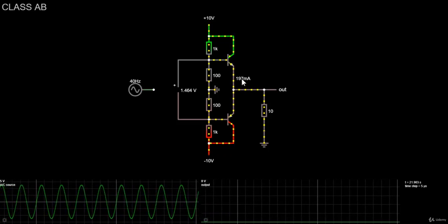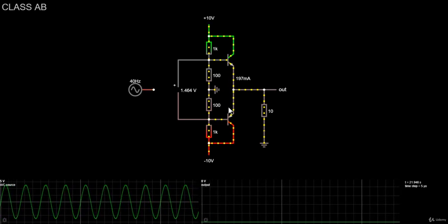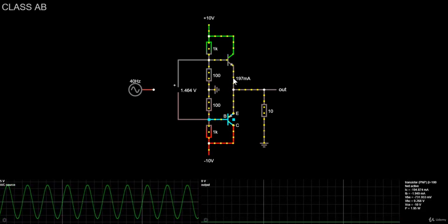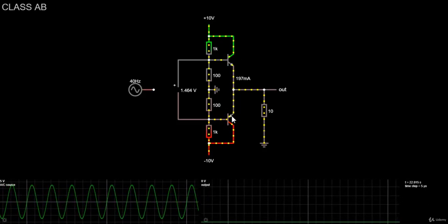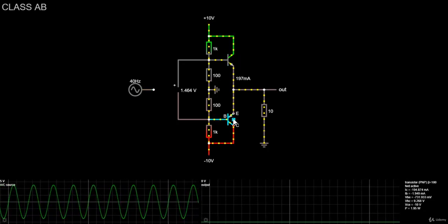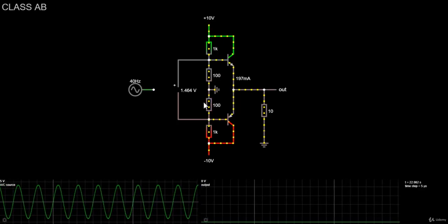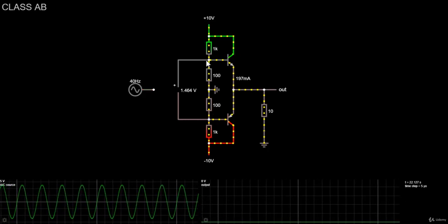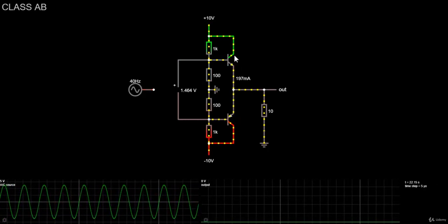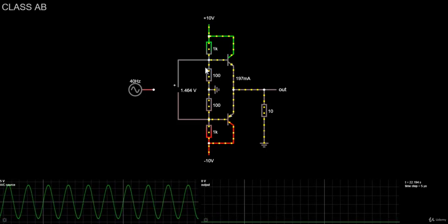We forgot to mention one important disadvantage of this circuit, and you might have already guessed it. The two complementary transistors need to be identical. Even though this is NPN and the other one is PNP, the electrical characteristics for both of them must be identical. So the main reason why this configuration cannot be used for class AB amplifiers is that the set of values of the resistors will only work for a particular push-pull configuration. Moreover, the set of values needs to be chosen very carefully, especially if the complementary transistors are different.